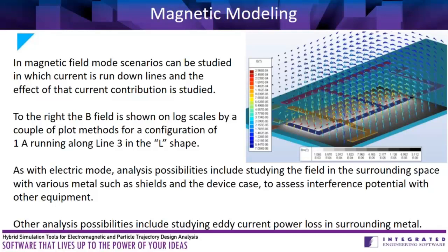If you're looking just on a plane and only interested in the magnitude, then contour plots can be nice. And I made this contour plot have a silver type of color scale so that it was visually distinct from the colored arrows that I put surrounding it. It's easy to see color-wise which is which. So you can see here that the magnetic field has a high value of about 1 millitesla right beside the line, and that decays.